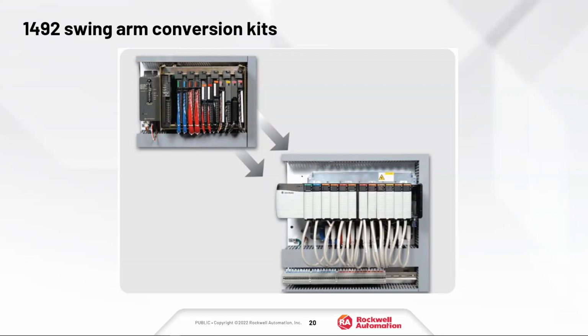It does add about 3 or 4 inches of depth to the PLC 5 chassis. So it's important when you're doing a PLC 5 swing arm conversion kit to accurately measure the space in the panel, especially the depth, to make sure that you have enough room in the panel to do it. So go ahead, Mike.